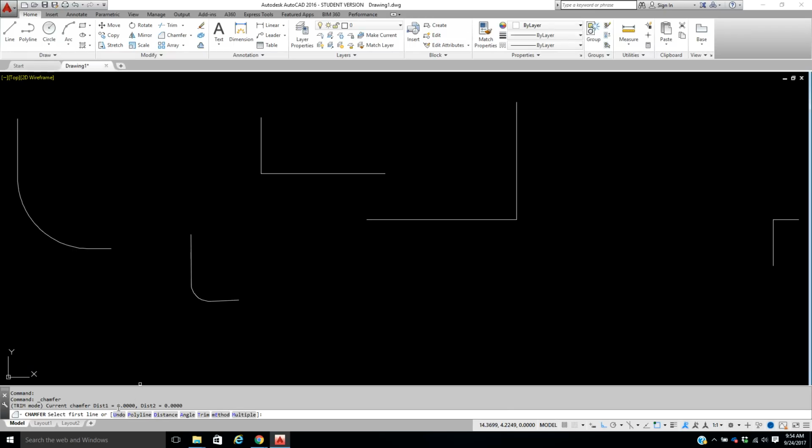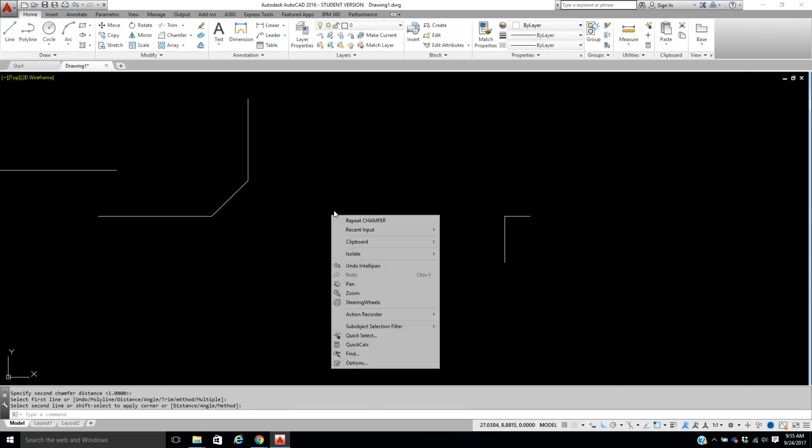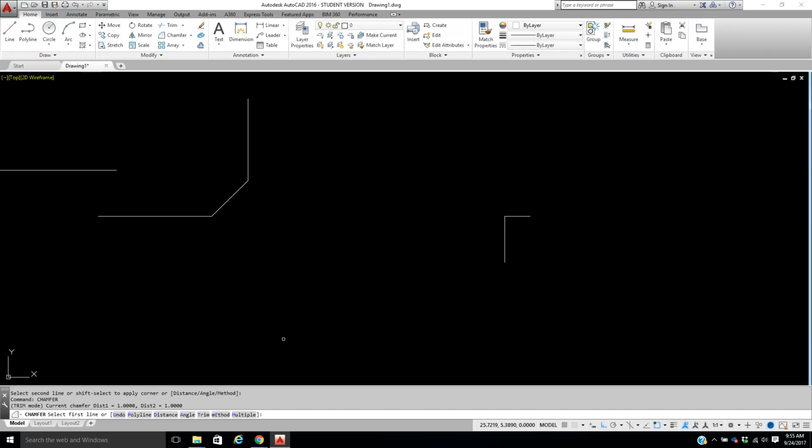With chamfer, you can do it as a distance or an angle. It's very much the same. If you do it as a distance, I can say my first distance, say I want it to be an inch, and my second distance, I want it to be an inch. I can come in here and pick here and here. Now, in order to get rid of it, I have to repeat chamfer, D for distance, or choose the word distance, and I have to go back to 0, 0, and then that will take this back where it's not going to have the line on it.